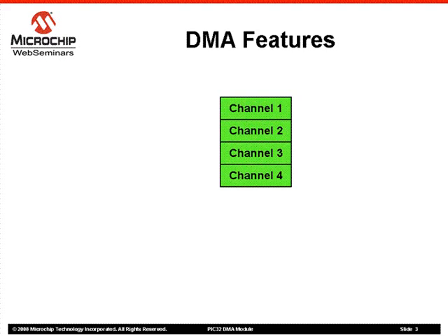As you might already know, the primary job of the DMA is to copy data from source to destination. The PIC32 DMA module contains multiple channels to simplify transfer management. The DMA module automatically cycles through all channels and schedules data transfers as resources become available. This slide shows 4 DMA channels. Refer to your device datasheet for available DMA channels.